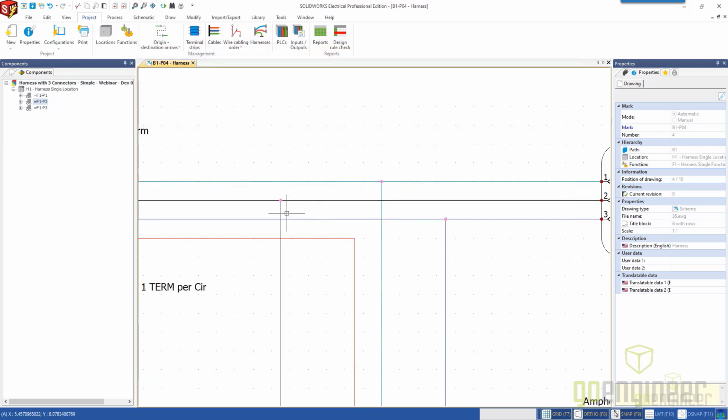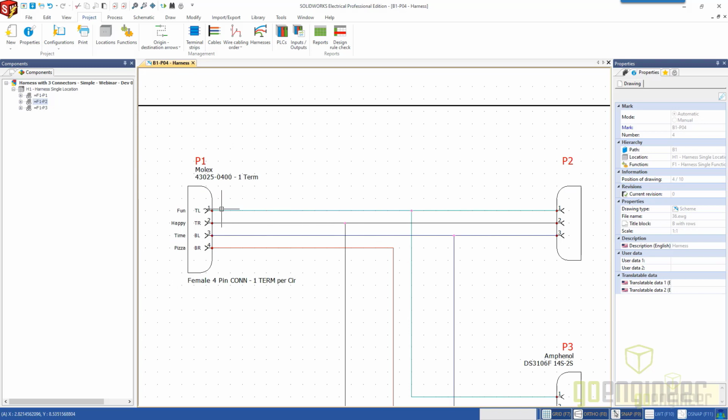The reason being is when we have wires intersecting other wires, I don't really know which way the majority of the wires are going. And no, this is not a splice. This is just saying I have one line indicating the other one. If we just look at the pin 1s and this green wire coming down, they're all pin 1s there, 3 locations, so you have to have 2 wires to do that.